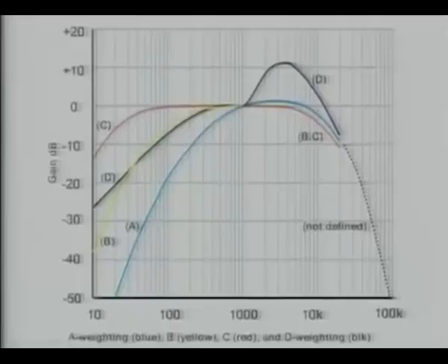At 6 kilohertz, the loudness perception is at a higher level compared to random noise, which is a broadband noise. So that is why you have this peak at around 6 kilohertz. Otherwise, it's again more or less flat. I wanted you to get exposed to some of these curves, and these curves could be translated into charts, the industry standard tables. You can use them and weight your sound pressure level measurements accordingly.